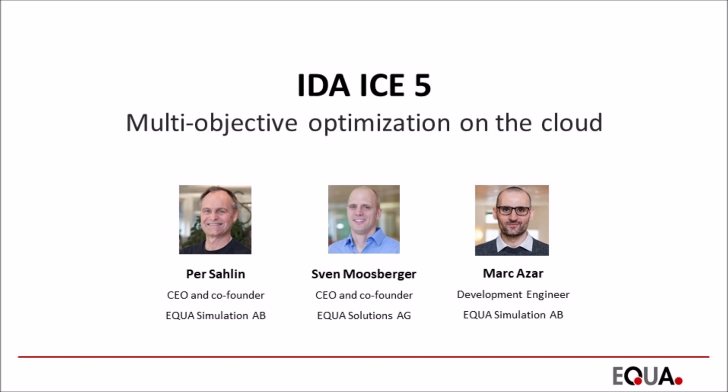And another question there is, how are the different output objectives prioritized in Automo? There are weights that you can set on objective functions, or you can use the graphical script for that. What about GenOpt? GenOpt doesn't prioritize, because you can only set one objective function in GenOpt.